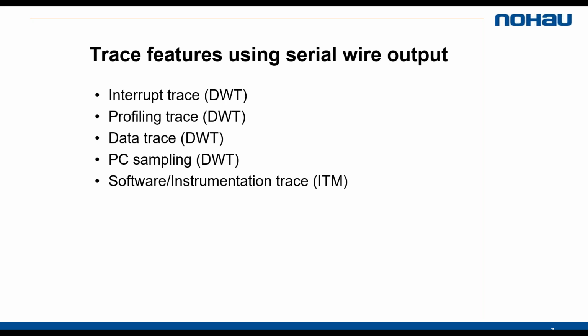That is more or less that you can see when the interrupt occurs and how long it takes for the interrupt handler to run to completion, or return, so to say. And you have profiling tracing, which is more or less that the ITM or DWT can output the value of some benchmark counters that are inside of the CPU core.